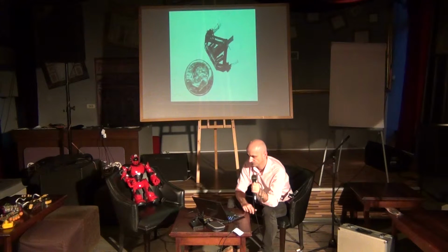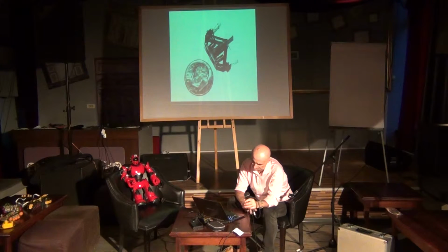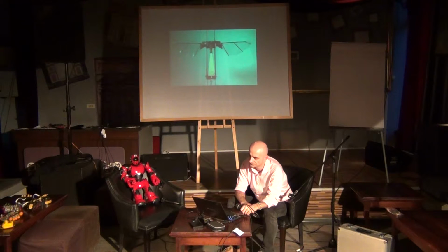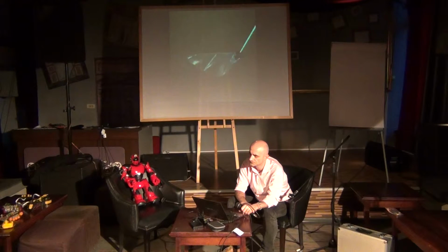Previous micro-robot designs have attempted to concisely control each wing trajectory in these two dimensions. The MAV described here has 3 degrees of freedom, only one of which is actuated. Here, a central power actuator drives the wing with as large a stroke as possible, and passive dynamics allow the wing to rotate using flexural elements with joint stops to avoid over-rotation.